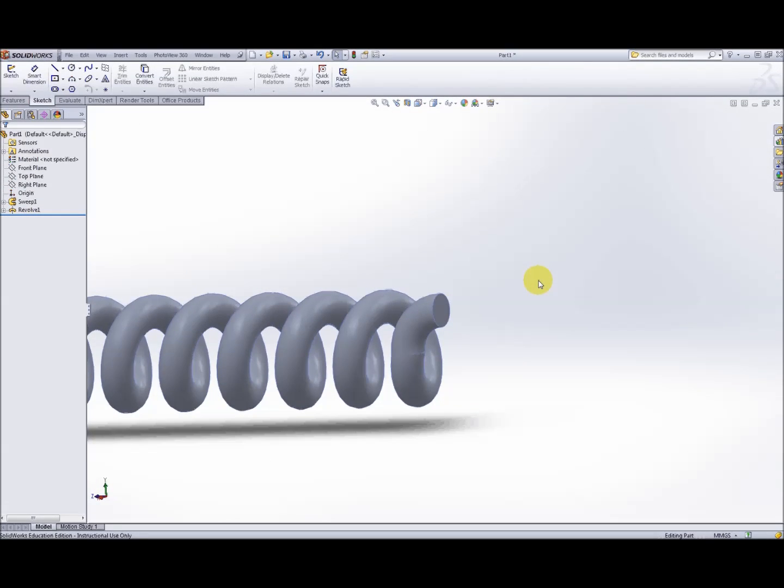So what we're going to create next is the continuation of the cable. We're not going to have the curly, we've done the curly section, so now we need to do the relatively straight section. Now if we just did a completely straight extrusion, this part would look very artificial. So in reality cables are never straight, and they always have a bit of a curl in them. What we're going to do is we're going to create what we call a 3D sketch as opposed to a 2D sketch. Now in the past we've always created sketches either on a plane or on a face, on a flat face. With 3D sketches we can create a sketch in 3 dimensions, so that means each point is in a different dimension. They're a little bit more complicated, and I think I said in the past don't use them. This is one of the few cases where they're actually very useful.